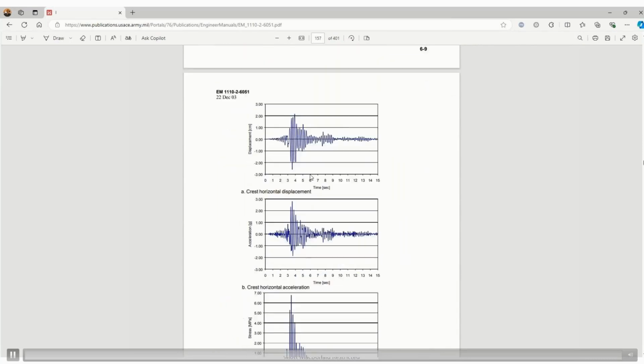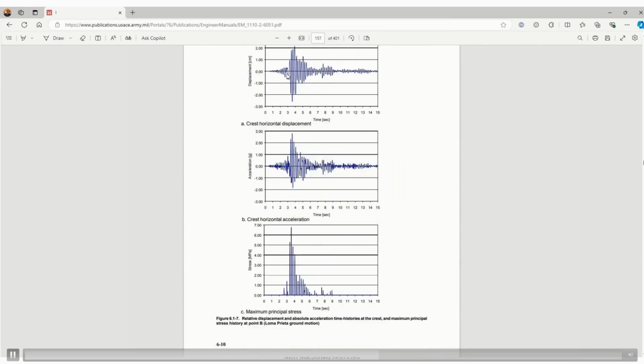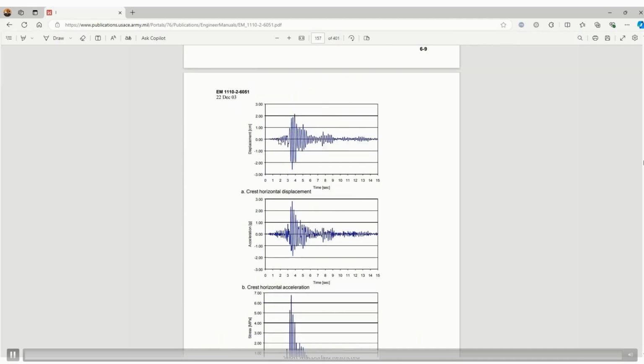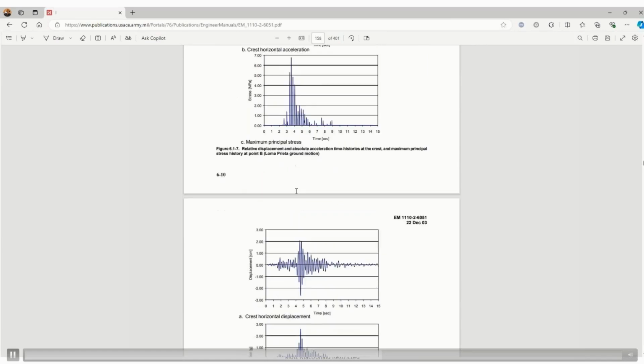So then for this conclusion, they have displacement time histories plotted. Okay, so they have also not used Rayleigh damping. How do I know that? If Rayleigh damping they had used, some mass proportional and stiffness proportional damping would have been there, so it would not have been symmetric about this line. It would have gone something like this.